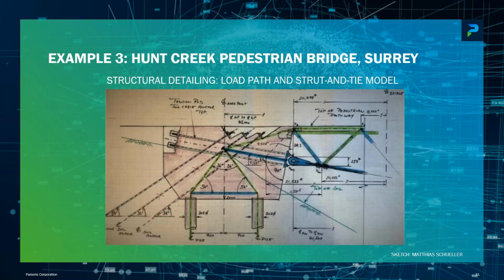Now, the reason why we developed this system was the city didn't want to cut down trees, and they wanted to keep the corridor as narrow as possible, and that provides not good access for crane or for heavy duty equipment. And what you see, this truss was supposed to be pre-assembled as sawhorses and flown in by a very light crane, and then this was all stick built together. You get a sacrificial form in the form of a corrugated metal sheet on top, and then you cast a concrete slab, make this top chord monolithically with the abutments, and in that moment, when the fresh concrete hardens, you establish the truss action. But all the dead load up to this moment goes purely to the suspension system.